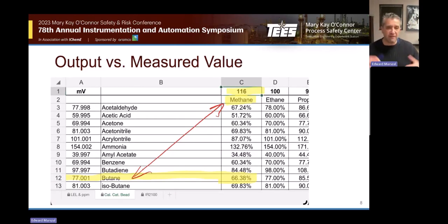Okay, so given that though, let's look at the next variable, which is going to be the measured value. Ultimately, the measured value is going to be in millivolts. There's going to be a bridge in the electronics for the device where the RTD for the reference and the RTD for active are on different sides of the bridge.